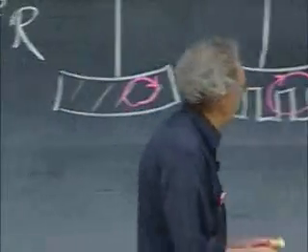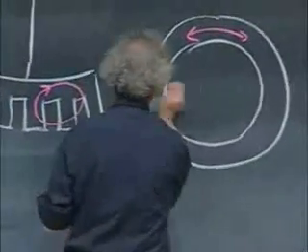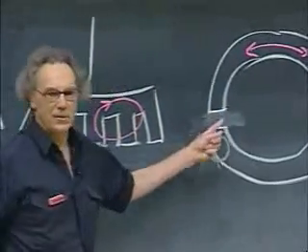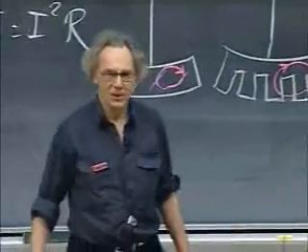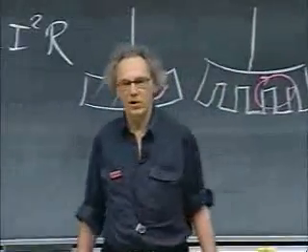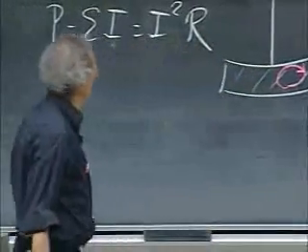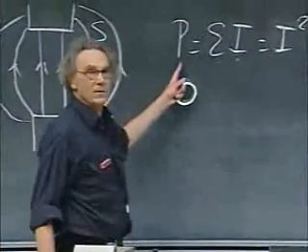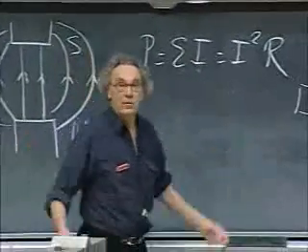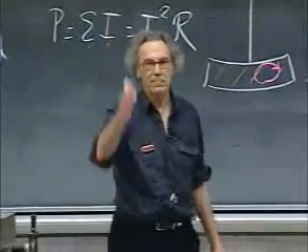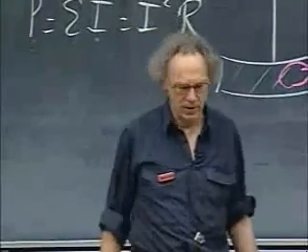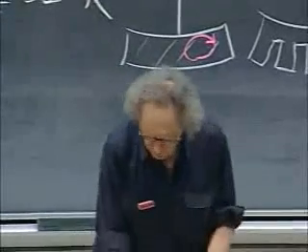And then I will throw through another ring, which is the same dimension, but this ring has an opening here. Air, the resistance is huge. So the eddy current that is going to flow is way lower because the resistance is so high. And so there is no power dissipation because I is so low, and so there is no heat produced at the expense of kinetic energy, so there is no damping. There is no strong force that opposes it. And I can show you both.